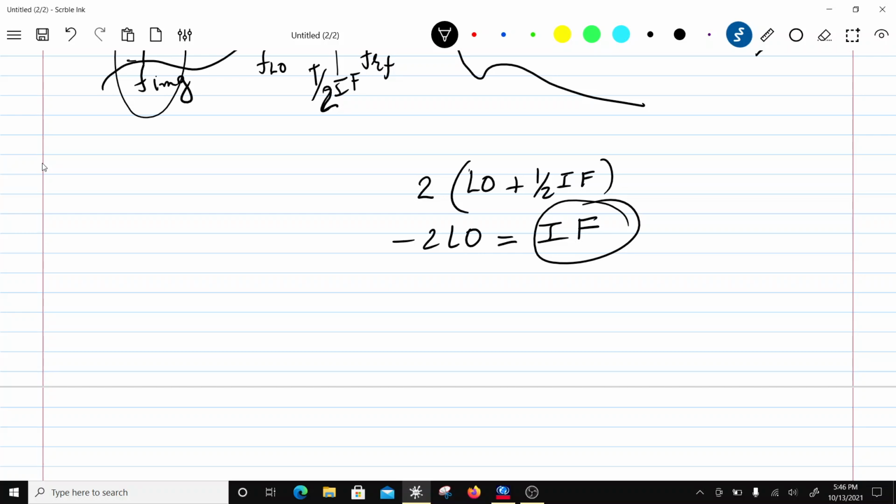So that's a much more severe scenario, and the image reject filter cannot do anything about noise coming from the bands. So the noise condition is much worse in case of direct conversion, because your filtering will not be able to get rid of that, right? So I hope you understand the difference between the two. What we are going to see is the situation in case of a direct conversion.